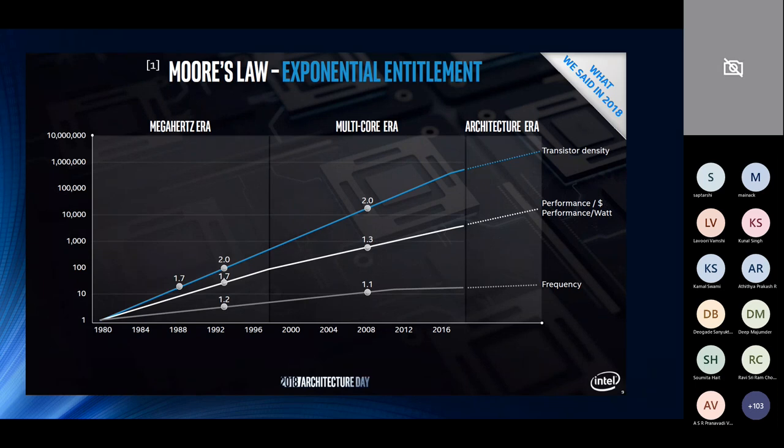If you keep on pushing for frequency, you hit a limit for power, you hit a limit for your thermal budgeting, for the traces you have on your PCB boards, you hit a bunch of limits from noise and signal integrity and whatnot. So we had a shift from being frequency driven to, you could say, core driven, or the way you integrate the system at a package level.